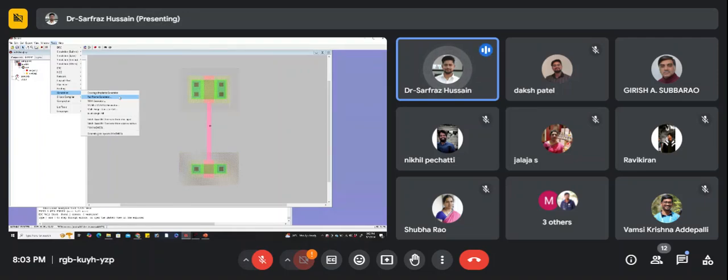Now here also what we are expecting you to do is you make up the layout, you do this DRC analysis, you do this ERC analysis, you do this NCC analysis. That means your DRC, LVS, parasitics. So all those three you have to complete. So after you complete all those three, then you go for the pad frame.